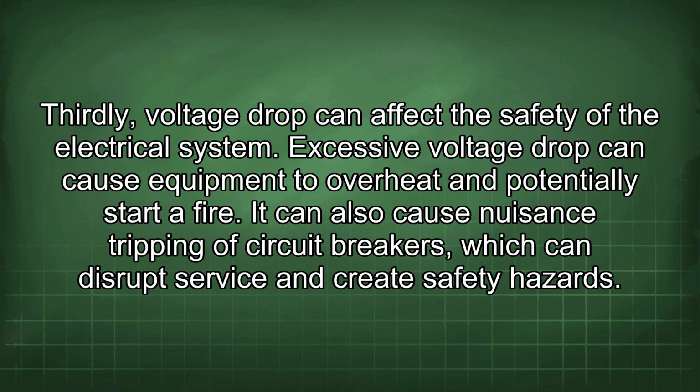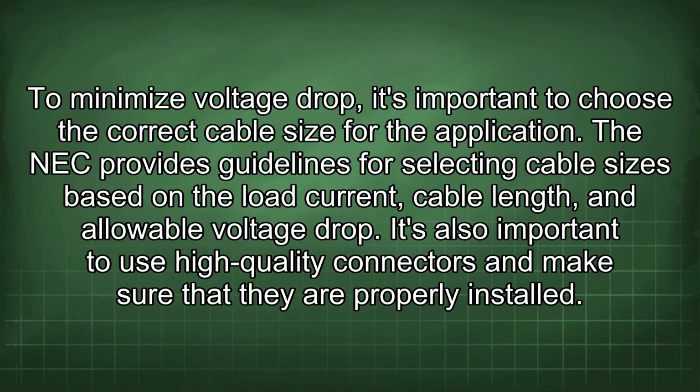Excessive voltage drop can cause equipment to overheat and potentially start a fire. It can also cause nuisance tripping of circuit breakers, which can disrupt service and create safety hazards. To minimize voltage drop, it's important to choose the correct cable size for the application. The NEC provides guidelines for selecting cable sizes based on the load current, cable length, and allowable voltage drop.